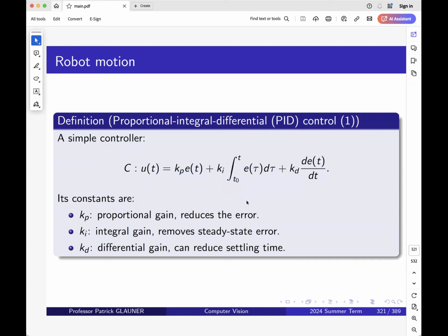But then we have made previous corrections because it's a closed loop system. So in the last loops, we had done corrections. And maybe if I just use the proportional one, then I'm maybe over and undershooting, as I explained before with the drone. That first is too low, but then too high, then too low again, and actually converges maybe slowly.